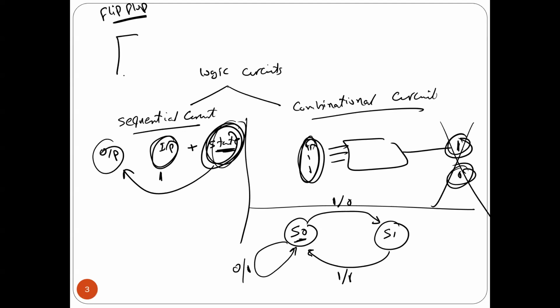So you have a circuit. I'm gonna teach how I design this circuit, but this circuit can store 1 bit. This bit can be 0 or 1. A storage unit that can store only 1 bit. We call it a flip-flop. Is that okay? I will give you more details. So actually what happens is that if your system has 2 states, I need only 1 flip-flop. Why? Because this is how I'm gonna store the state. Simply because if the flip-flop is storing 0, so I'm in state 0, okay? But if the flip-flop is storing 1, so I'm in state 1.